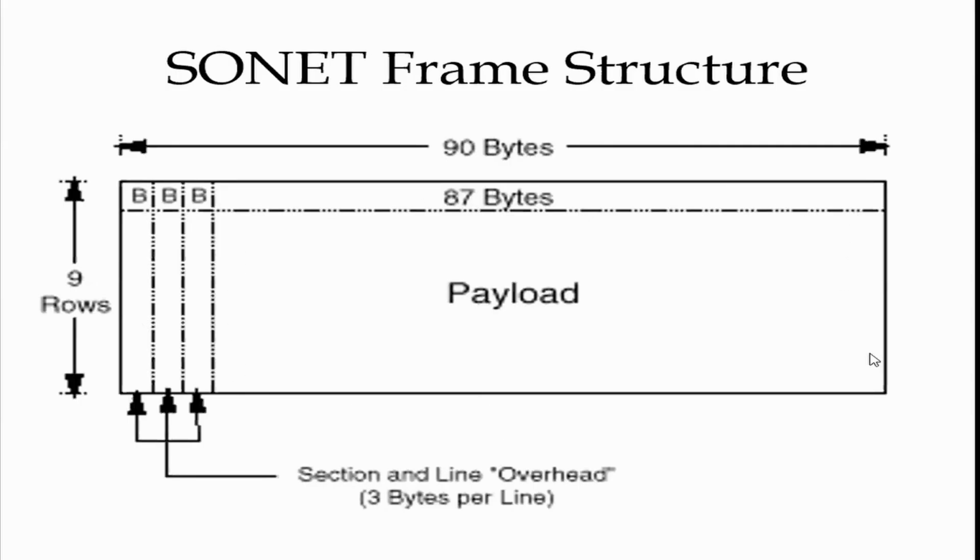So this entire frame can be transmitted over 125 microseconds. Within 125 microseconds, it will be transmitted from transmitter to receiver whenever this frame structure is followed. So this is a standard for fabricating a frame. Only if there is a defined length and width like this, it can reach the receiver within a particular time delay. That is, within 125 microseconds it can reach the receiver.